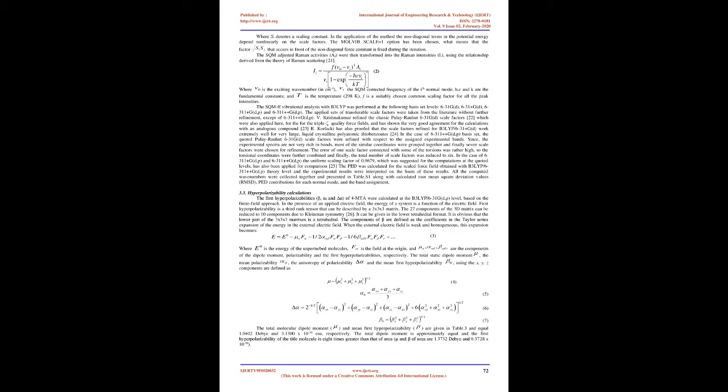The two-dimensional relaxed potential energy surface scan, using internal redundant coordinates, through the opt=modredundant option, has been performed for the angle C12 S11 C1 C6 and C5 C4 O16 C17 at the B3LYP/6-31G(d,p) level of theory, using Gaussian 09.